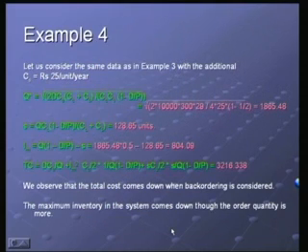Now let us consider an example to compare models 3 and 4 because they are very similar. So we consider the same example with an additional data that Cs is rupees 25 per unit per year, the same Cs that we used in example 2. Now going back and substituting Q star, the economic batch production quantity is now found to be 1865.48. The quantity back ordered is 128.65 units, going back to the same equations.